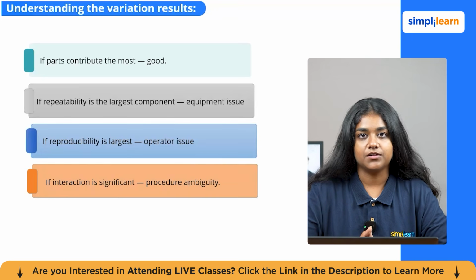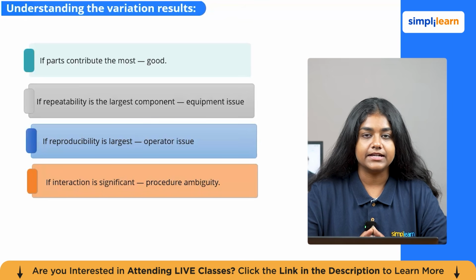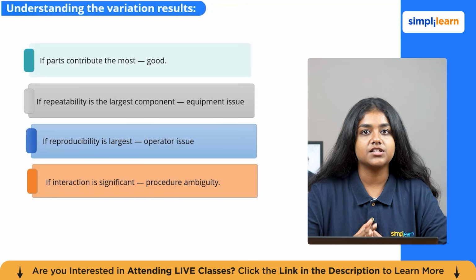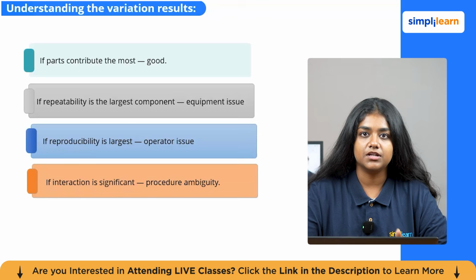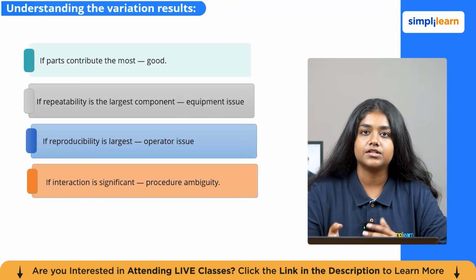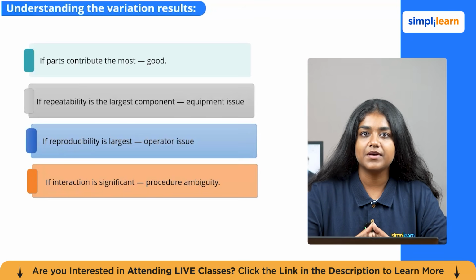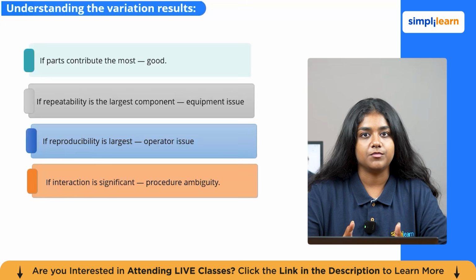Clarify the measurement method. So apply the same acceptability guidelines as the X bar and R method. Percentage ERR under 10% is acceptable, 10 to 30 is marginal, over 30 is unacceptable. And act on the specific source that is contributing most of the problem.